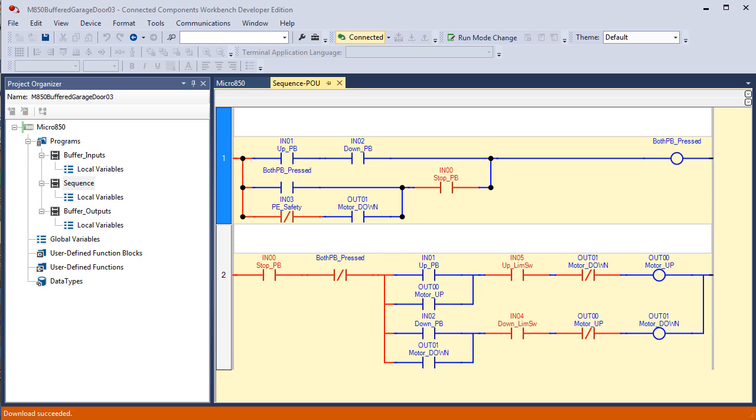So right now our photo eye is blocked, so I'm going to turn it off, change the state of it. One thing that I just noticed, and is probably an improvement in version 11, is the color of the text. You probably already noticed it, but because I'm a dyed-in-the-wool RSLogix guy, where the text doesn't change color, I just noticed that if the bit is on, the text is red. If it's off, it's blue. Notice with input 3, our photo eye, the instruction is false because input 3 is off. Input 3 is on, see it changed to red, and the instruction is false.